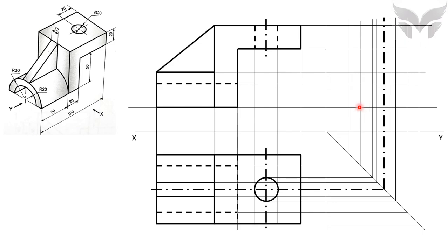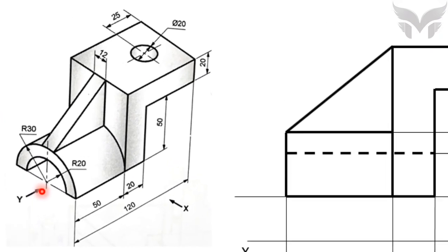Alright, now to draw left hand side view, let's imagine that you are looking at the object from Y direction. Then imagine how it will appear to you. Again, for ease in imagination, let's focus on a semi-cylinder again and observe it from left hand side. You can see two concentric semicircles highlighted in red color. To draw these two semicircles, we need to know the center point of them.